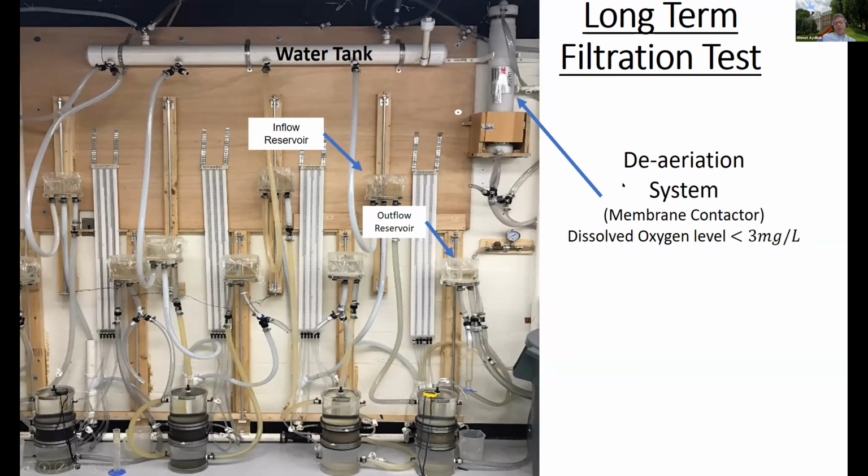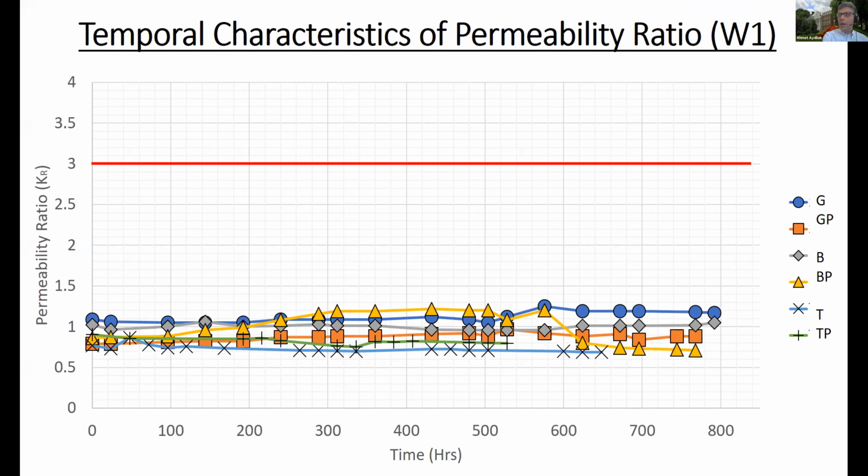These are constant head hydraulic conductivity runs. However, one has to be careful that you need to use a deaeration system, because oxygen contents inside the tap water can be quite problematic when you are running any type of clogging test with the textiles, because air bubbles sitting on or inside the textile or around the textile can basically skew the values. So, a system that allows the continuous deairing of the water is required.